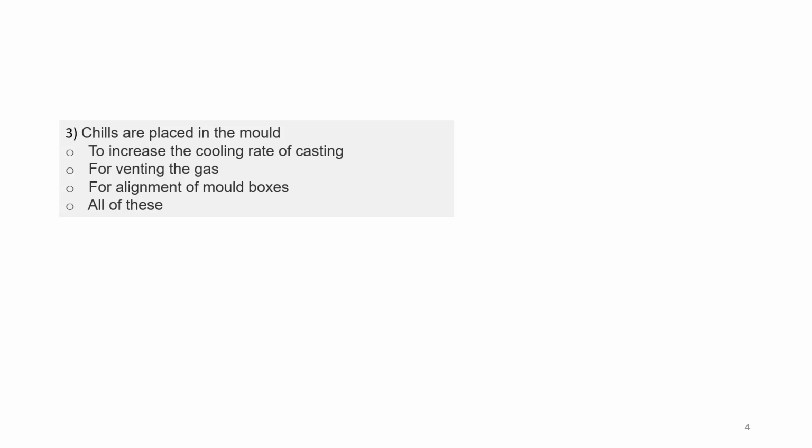Next question is, chills are placed in the mold. Your options are to increase the cooling rate of casting, or for venting the gas, or for alignment of mold boxes, or all of these. So which answer would be correct? You can type it in the chat box, or you can unmute yourself and tell what should be the answer.